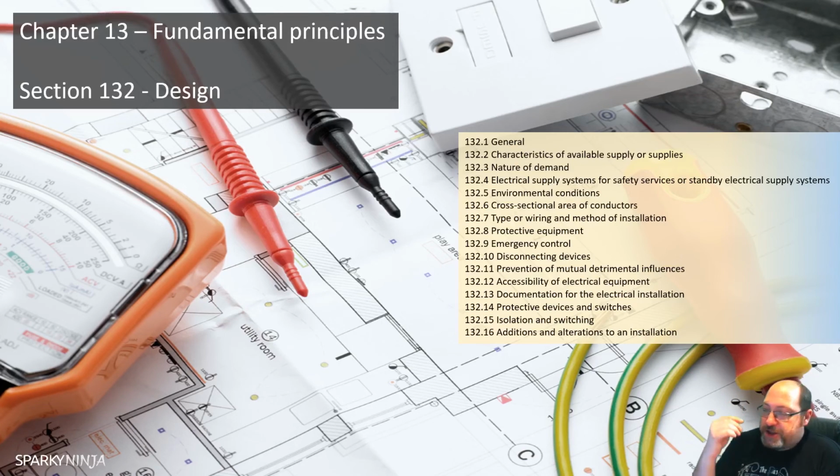Which means in English, when Doris goes to B&Q and buys a light fitting for her bedroom, and she goes to install it and realises she doesn't know what she's doing, she finally calls an electrician out. When the electrician realises that a luminaire is going to go in, it's going to add demand to an existing electrical system, you're going to then have to consider the additional alteration, and you may then have to look for the presence of earthing and bonding under her sink. And she'll then just start thinking that you're trying to pull a fast one.